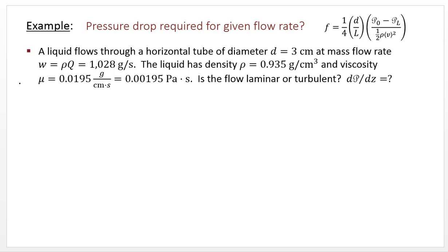We can use the Blasius formula, for example. It's convenient and it works for this range of Reynolds numbers. Blasius formula is accurate when Reynolds number is between 2100 and 10 to the 5. We have 2.2 times 10 to the 4, so it lies within that range, and this is a very simple one to use.